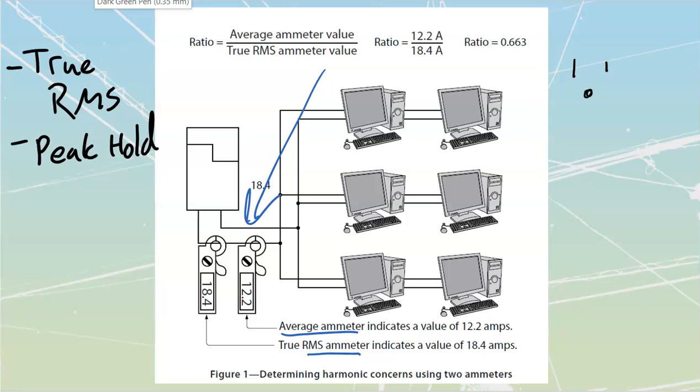What I can do is, if I have something else that is operational, so I've got a set of receptacle circuits over here, we'll just put this one in up top over there. And I've got a load that is connected into this one right now. I can check what I have for voltage going across from my neutral, that's the big slot, over to my bond that I'm going to have over here. We're not checking continuity. There should be a small amount of voltage drop because all of that current does still have to travel down the neutral over to my supply and back.